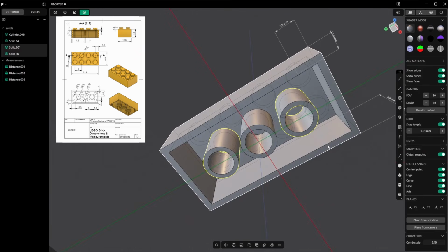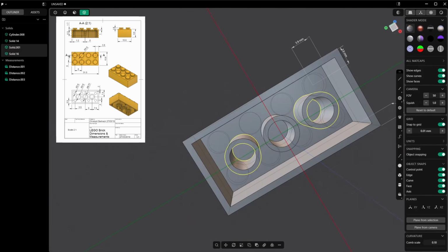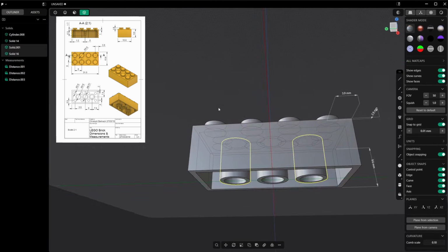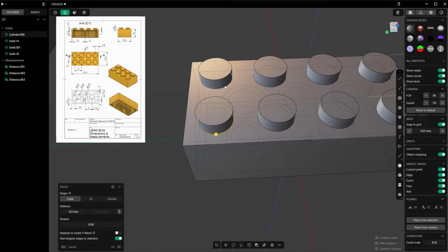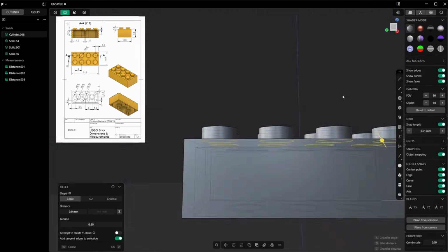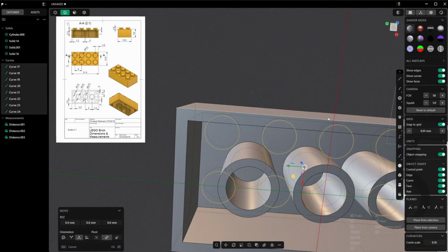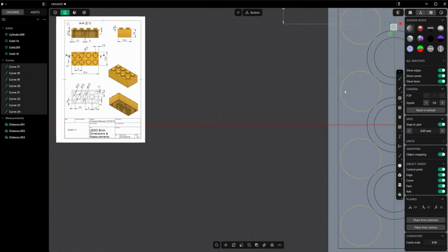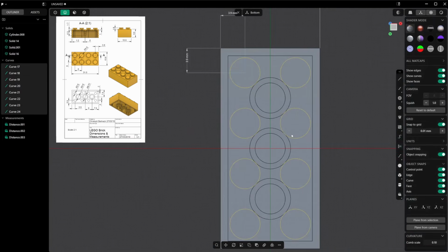We're almost done. I got all 3 of those. We still need to add the extra insets to the bottom, so I'm going to select all of these. So 1, 2, 3, 4. Oh, by the way, if you don't know how to see through, it's Alt Z, which is this one, X-ray mode. I'm going to select all these. Shift D. Then I'm going to go back to the bottom view so that I can see them all pretty well. I'm going to press the equal sign so that I can set the exact diameter of this circle. And it's going to be smaller than the top one, so 2.6. Enter. This is going to change them all, obviously.